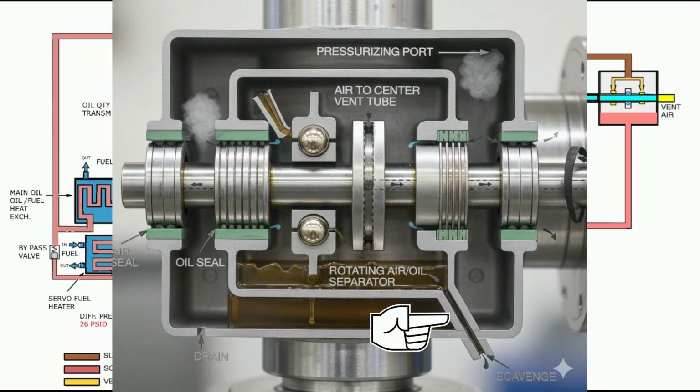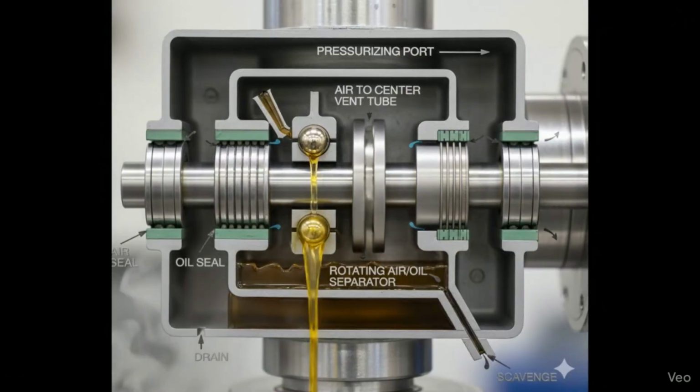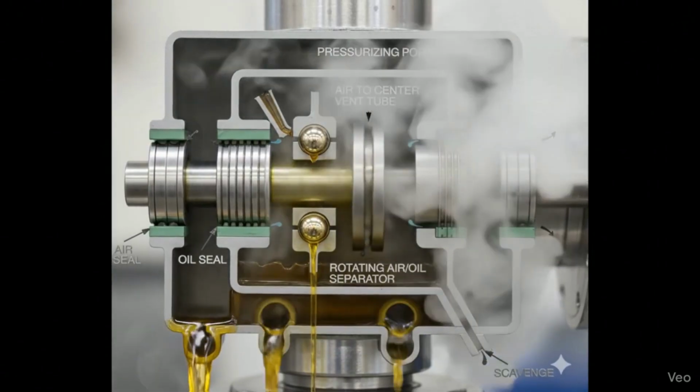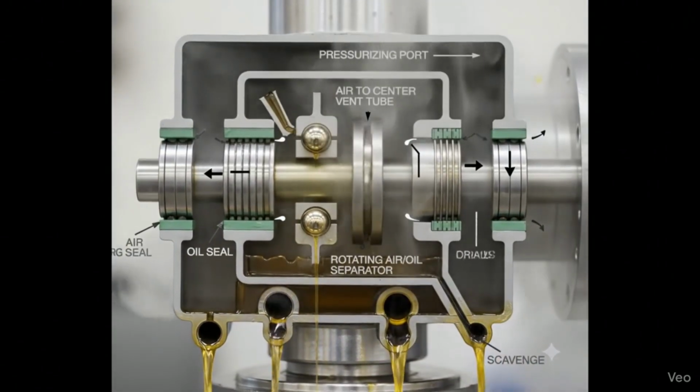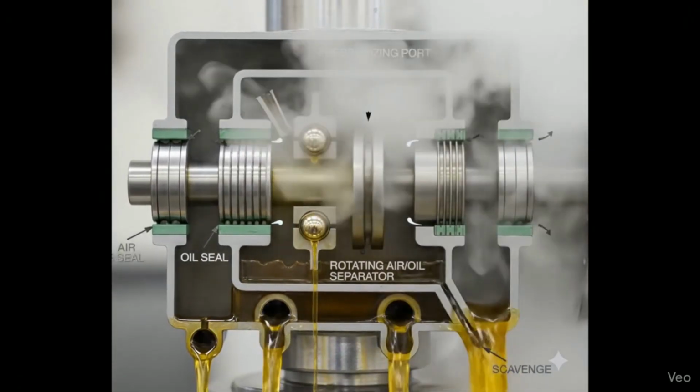In summary, the venting and scavenge circuit collects oil vapors to balance the internal engine pressure. It separates the air from the oil and oil vapor. While the separated air is discharged, the recovered oil is recirculated into the system.